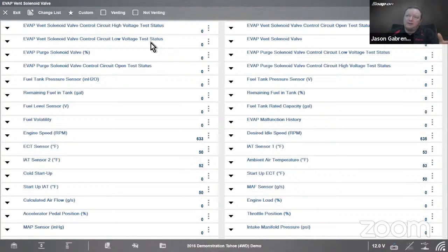So we can also see how the smart data filtered it down so it all fit on half a screen. In this case, we can monitor the data if we wish while we're doing the functional test. We can also use our 5 senses while we do this. We can go back to wherever the solenoid is on the vehicle, click venting, click not venting, since we are wirelessly connected up under the dash, so we can walk around. Does it click? Put my hand on it. Does it click? Listen to it. Does it click? All right, we can tell that just by doing this functional test.